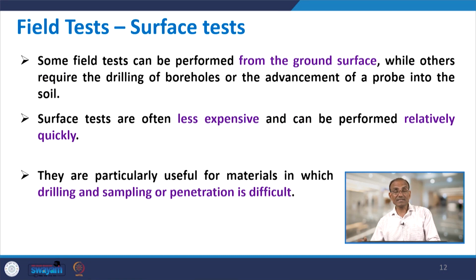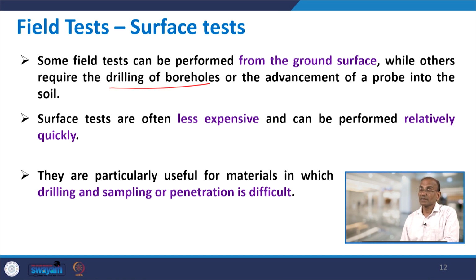Now, in the field test there are some tests which can be conducted from the ground surface, without drilling. If drilling of boreholes is not required, then it becomes easy, and there is no advancement of a probe into the soil. Surface tests are less expensive and can be performed relatively quickly.